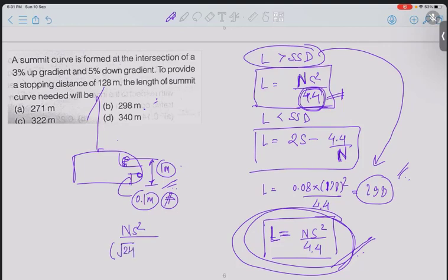Actually, they assumed certain dimensions of the vehicle, with the headlight height about 0.15 above the road, and the eye of the driver around 1.5 or so. So that is partially correct. Satish is correct about the way this is calculated. It is calculated based on the eye height of the driver and the headlight height of the car.